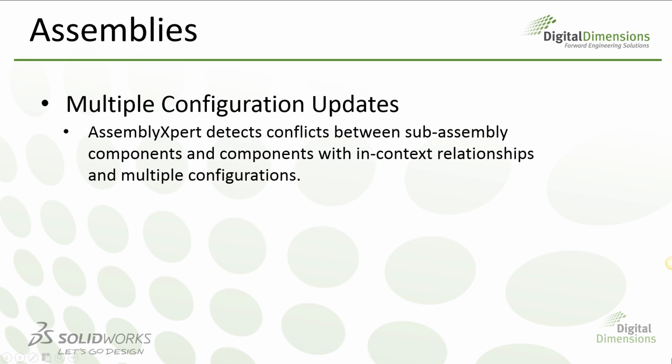The Assembly Expert tool now detects conflicts between subassembly components and other components with in-context relationships and multiple configurations within the assembly. This helps avoid those in-context relationships incorrectly propagating to the individual components, even though they may be a different configuration than other instances within the assembly.